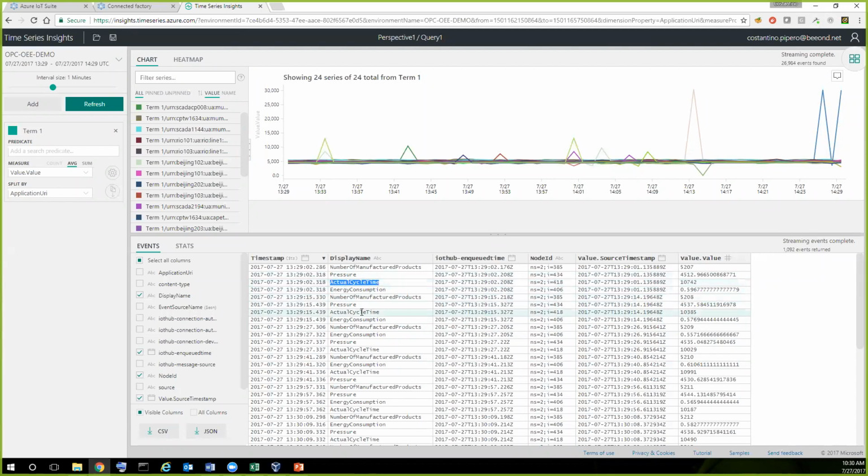A system that doesn't need to monitor a temperature every half a second, but needs to know about the cycle time, energy consumption, product counts. These are the information that are aggregated at the edge. As you can see from this list, which is represented by OPC UA nodes, what we call the edge is busy making decisions. And this is just one aspect of it, just to support the OEE calculations. So your OEE is calculated on-site and is maintained on-site.